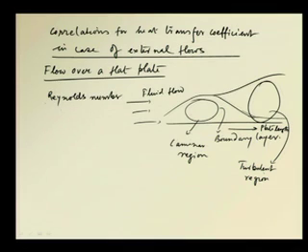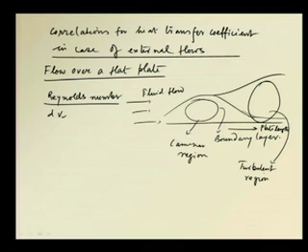We have seen that particularly for flow through pipes or tubes, the Reynolds number is defined as d V rho by mu, where the concept of V infinity does not arise; it is the average velocity V. This becomes the Reynolds number based on the diameter of the tube or pipe, where d equals d equivalent in case of non-circular ducts.